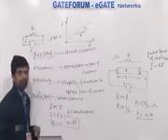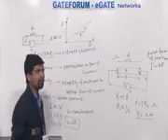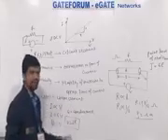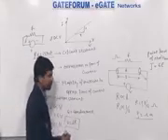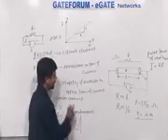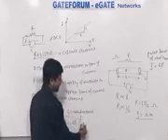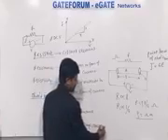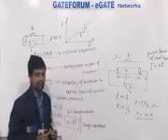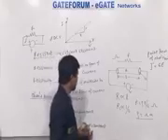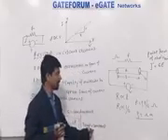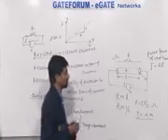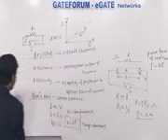Now many times in interviews they will ask what is the Ohm's law condition. So it is applicable to linear circuit elements. The second important point is that Ohm's law is applicable to linear elements where temperature is constant. It is not applicable to non-linear circuit elements. So if we consider a non-linear element such as a transistor, then at that time we can create an H parameter model, but we can't directly apply Ohm's law. So Ohm's law is applicable to linear circuit elements.